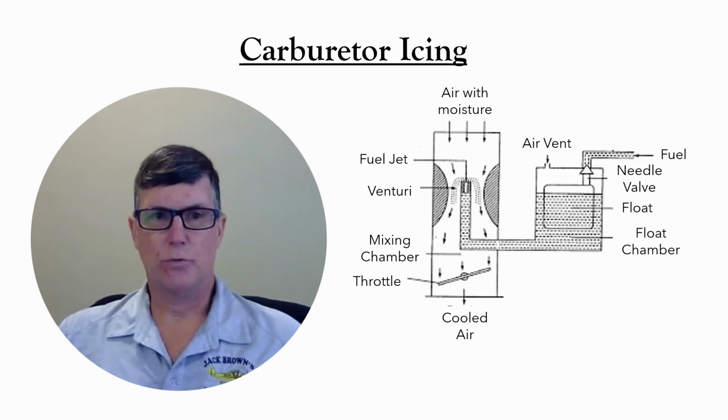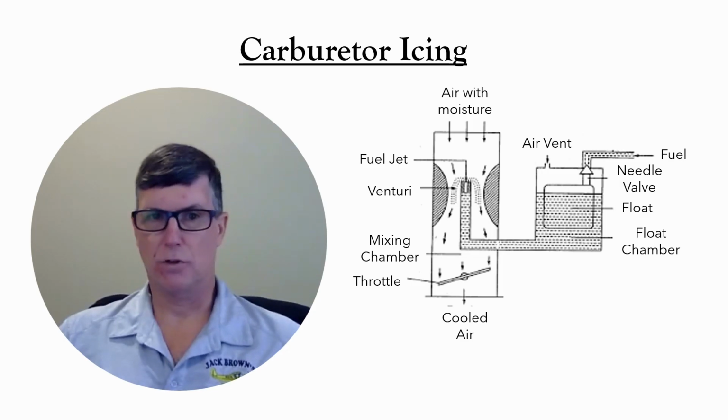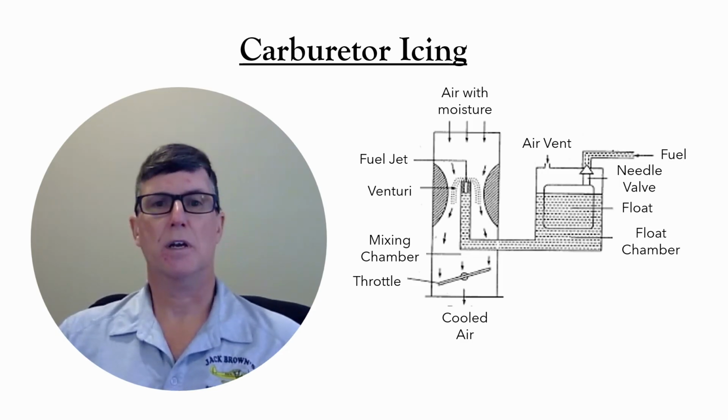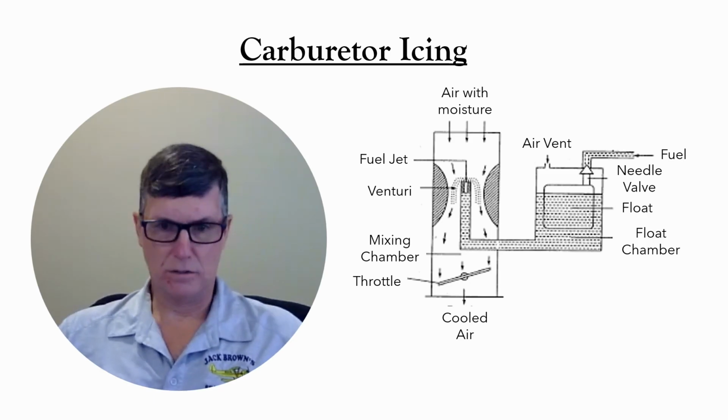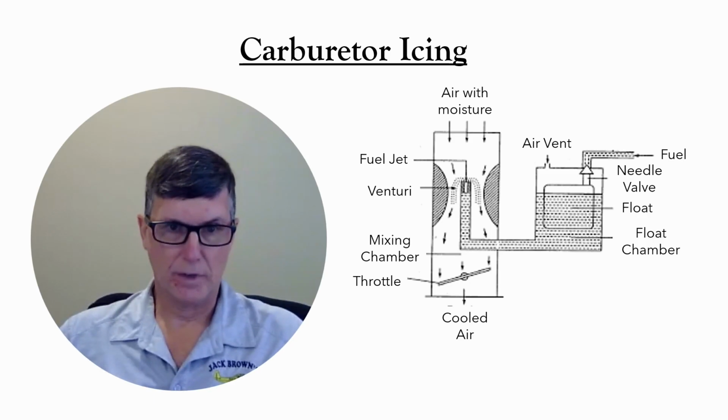Ice forming around the throttle will further restrict the airflow. It's like closing the throttle further. That causes a drop in power, and it causes ice to start forming even faster.